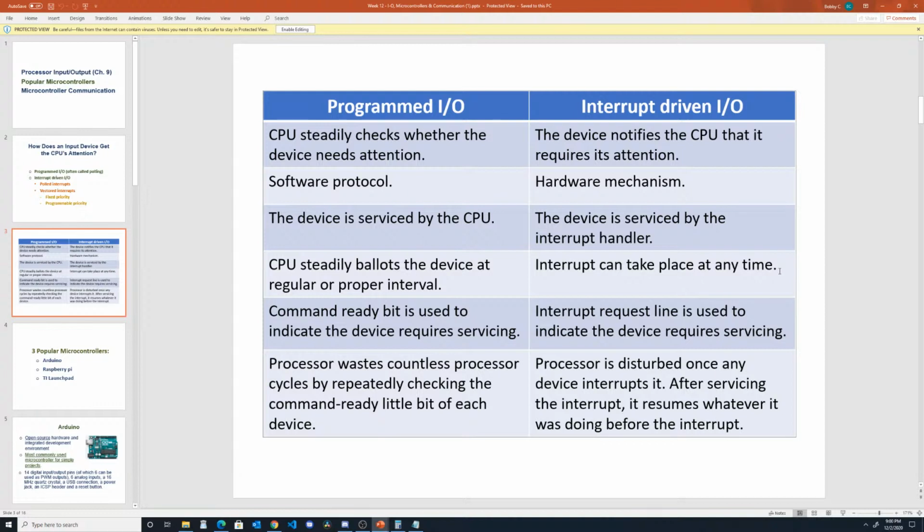Well, when you have a polled IO, it's constantly checking, and if the value changes in between when the CPU polls it and checks the value, it won't know until the CPU eventually does the check again.